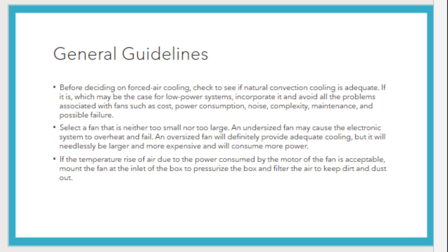Select a fan that is neither too small nor too large. An undersized fan may cause the electronic system to overheat and fail. An oversized fan will definitely provide adequate cooling, but it will needlessly be larger and more expensive and will consume more power. If the temperature rise of air due to the power consumed by the motor of the fan is acceptable, mount the fan at the inlet of the box to pressurize the box and filter the air to keep the dirt and dust out.